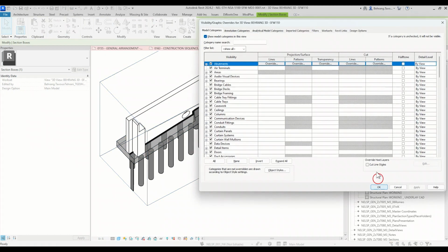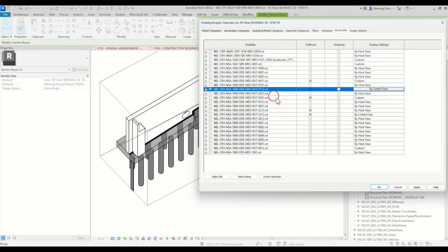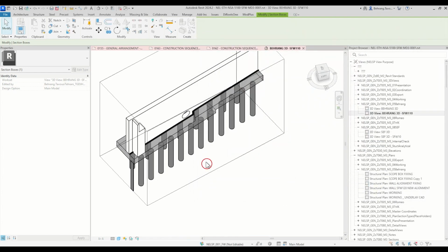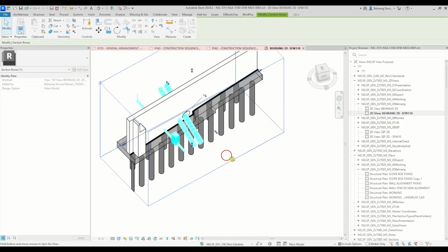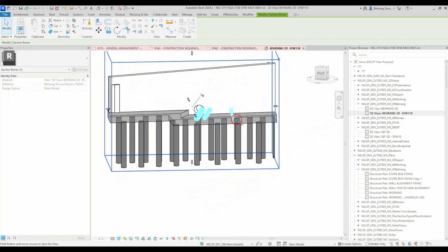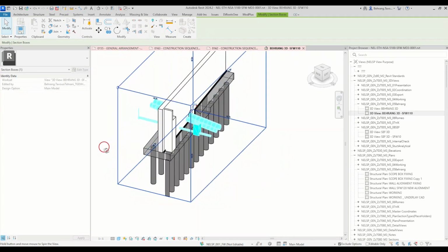So, typing VV. So on Revit links, our Revit link for those drainage pipes is this 112. And let's see, yeah, now I need 3 penetrations. It's not 1 penetration, it's 3 penetrations.